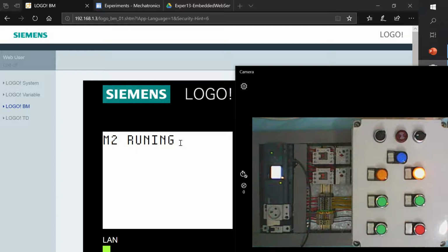However, in this PLC program, we can do so by reading the overload inputs individually. That's why they were dealt with as separate inputs rather than being just ORed electrically and entered into the PLC as one input. So this is the advantage. However, we have to use extra inputs to have such a privilege.